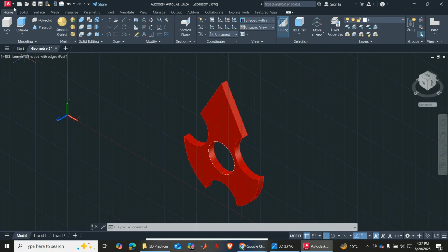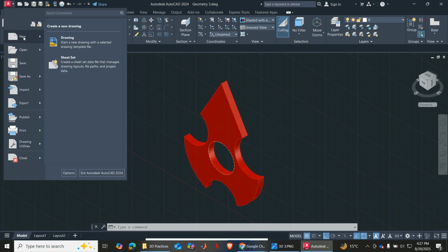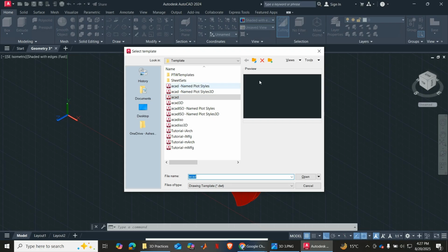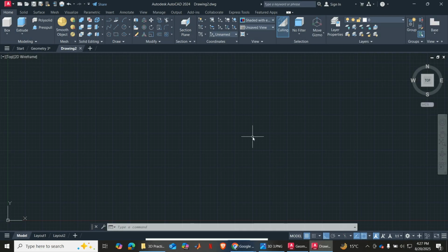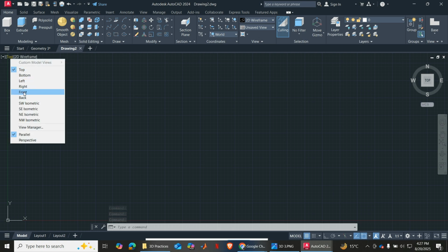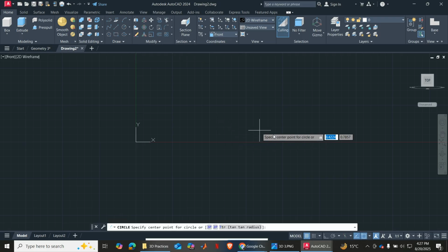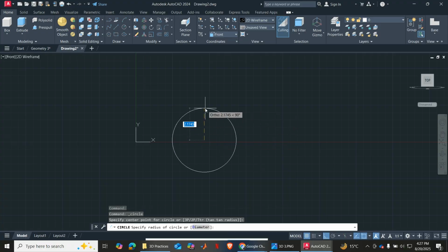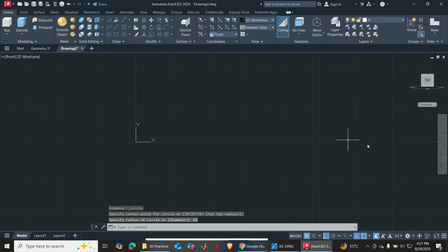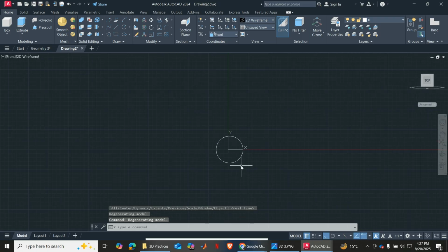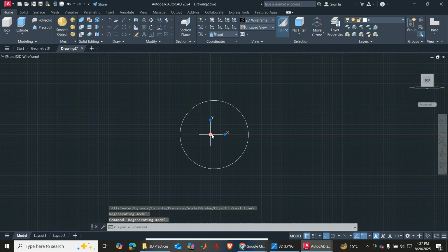So we come here, we say new, yes, this is the drawing ground, open, all right? And then from here, let's say front view, and then we start with the two circles. So ortho mode on here, then center here. So let's say circle, center here, radius 42, enter. So zoom to extent like this, where we can see it. Then we can move from here to there.